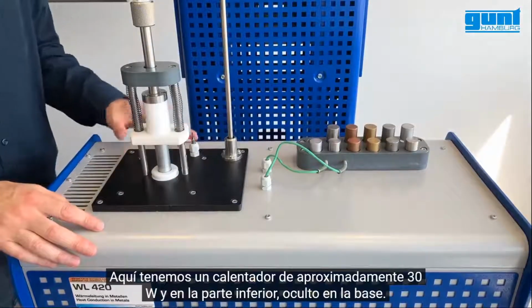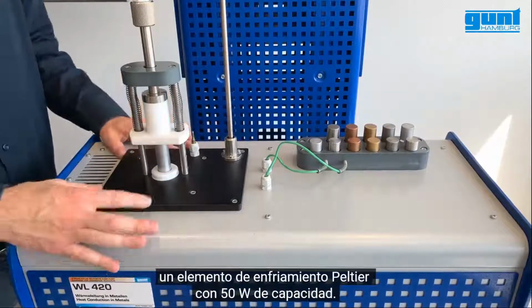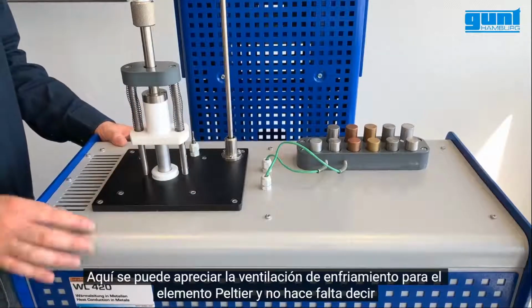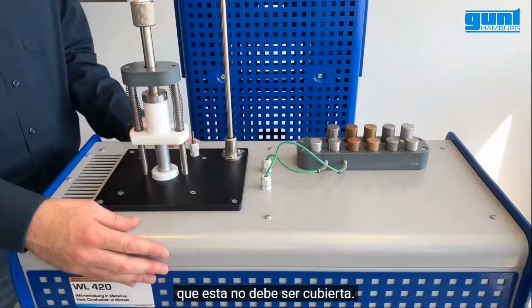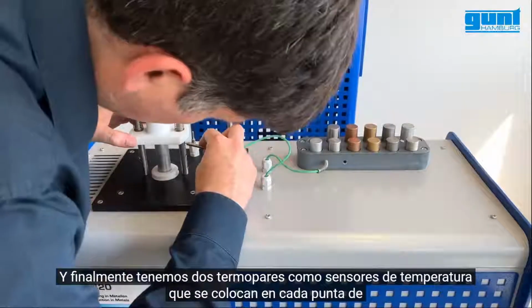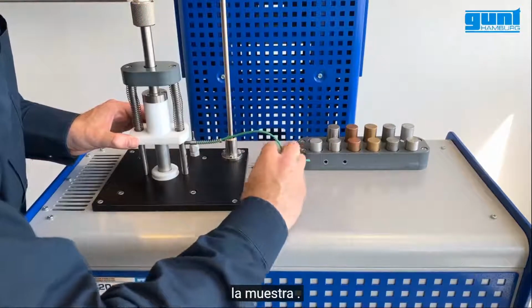Here we have a heater of approximately 30 watt, and at the bottom, hidden in the base, is a corresponding Peltier cooling element with 50 watt capacity. Here you can see the cooling grill for the Peltier element, and it goes without saying that this should not be covered. And finally, we have 2 thermocouples as temperature sensors, which are placed at either end of the specimen.